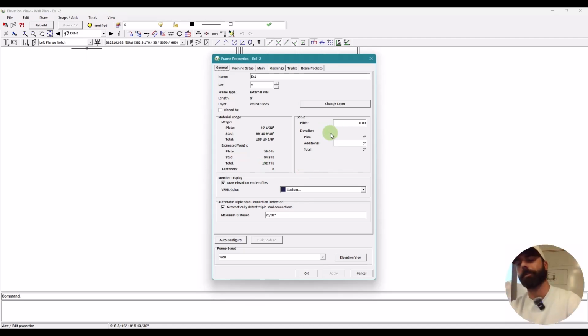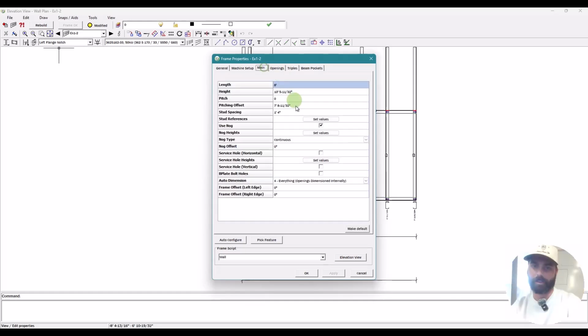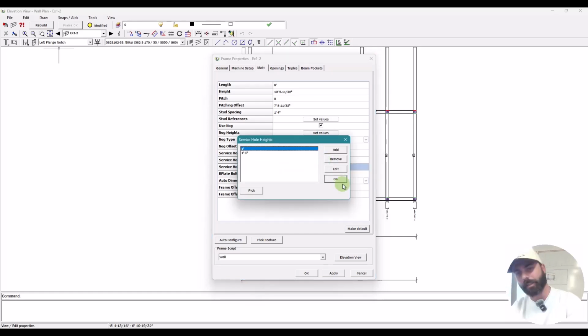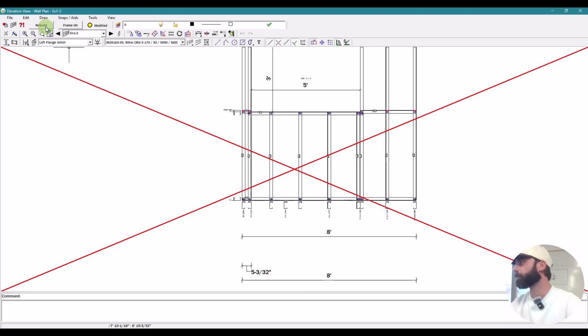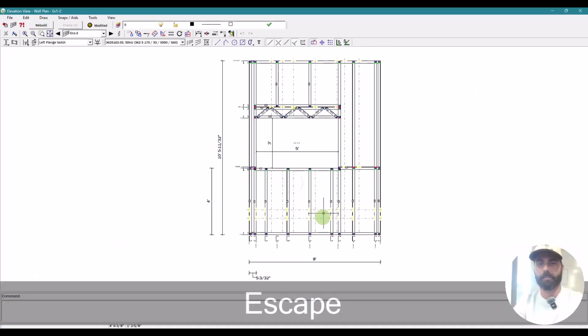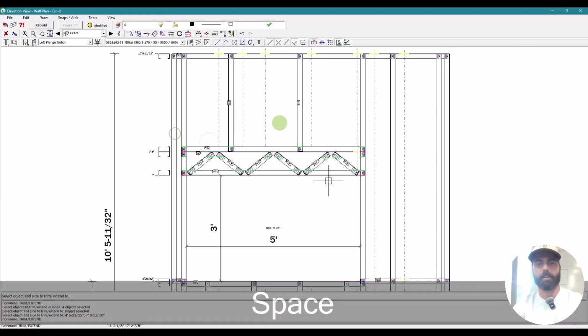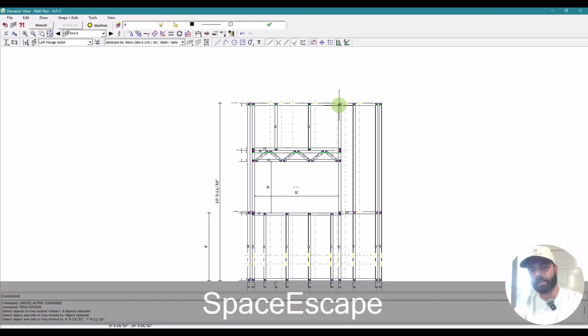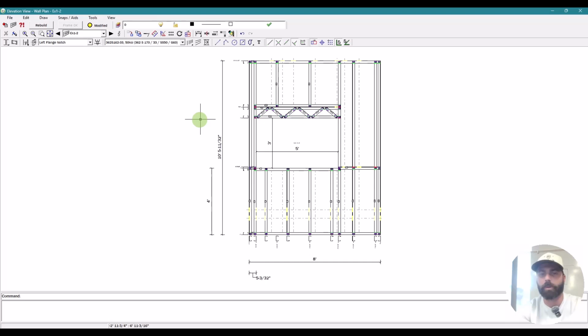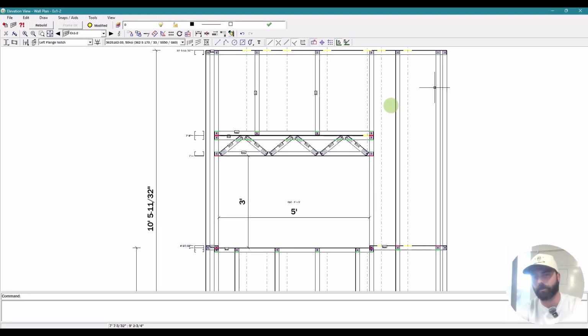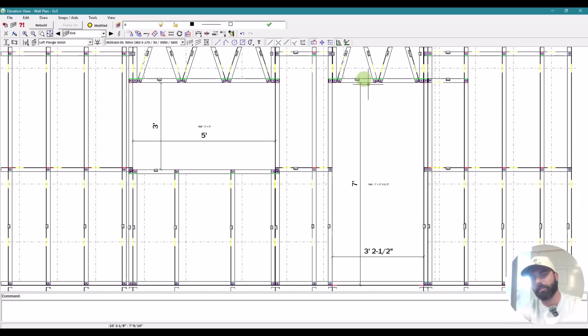The other thing is you can draw service routes and route things up and over openings. So if we knew that there was nothing on our other wall, this one isn't a very good example, but we probably wouldn't run the service holes through the header this close to the bottom of the webbing because it removes quite a bit of material. If we're running it through one of these ones that we could go up and over on a head split, which would have been like this window, then because there's no horizontal service studs, we might just have that there. Oops, wrong tool.